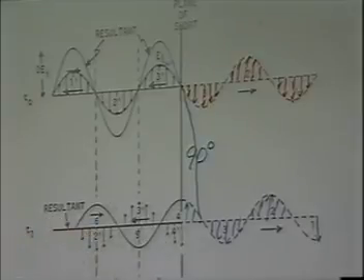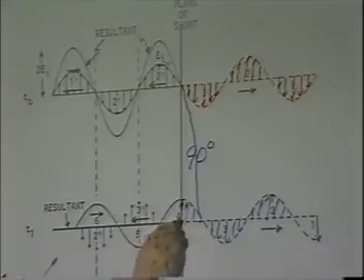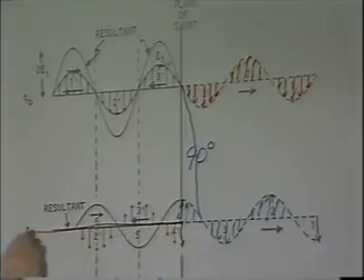Now look at this. If you stop at this point and look at everything on the line, you can see that the voltage is always 0 here. So here you have an incident wave and a reflected wave. The two of them have to add up to 0. You'd have the negative here, and of course that's 0. I think all of you see that if you look at this and add all of these up, the resultant is 0 all along this line.